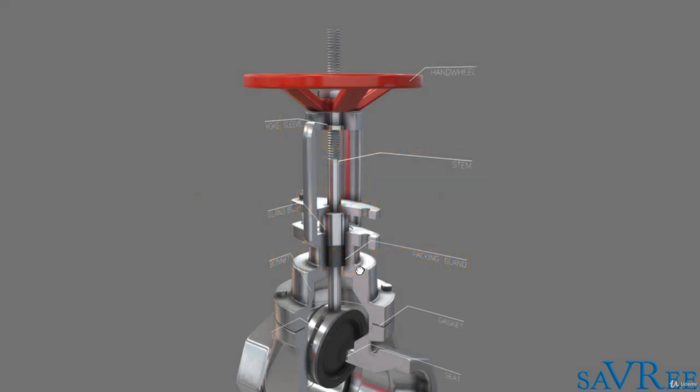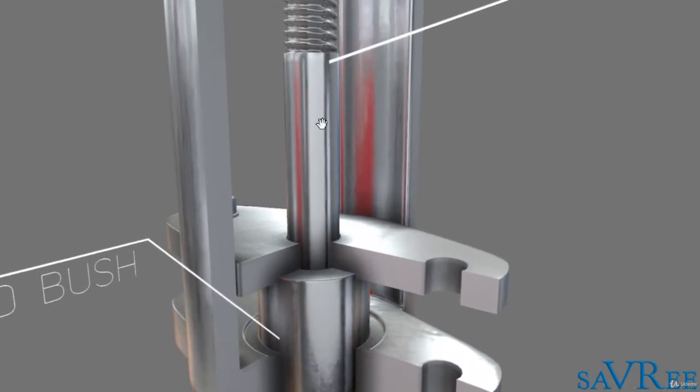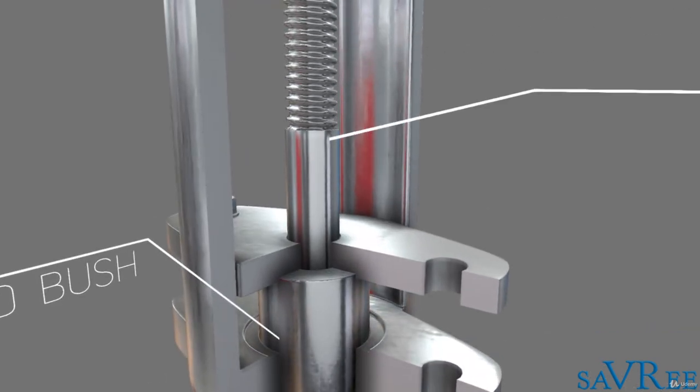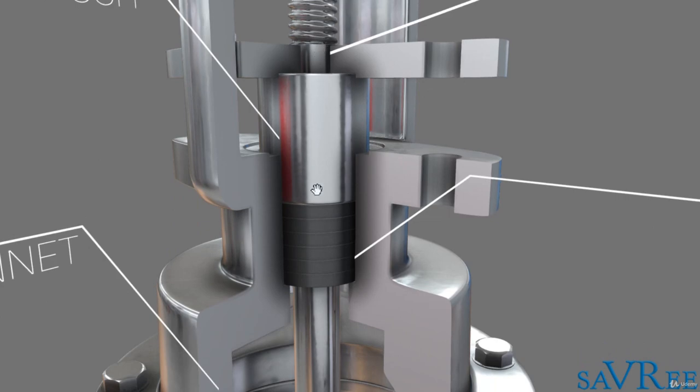The downside is that sometimes you will carry bits of dirt on the stem here, and when you close the valve, like now, the dirt, etc., will pass through the packing or potentially damage the packing, which will damage the seal, and maybe then you will get a leak. So contamination is a potential problem with rising stem gate valves, but the big benefit is that you can actually see visually if the valve is fully open or fully closed.